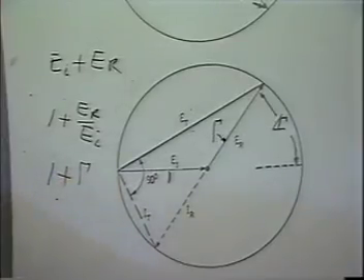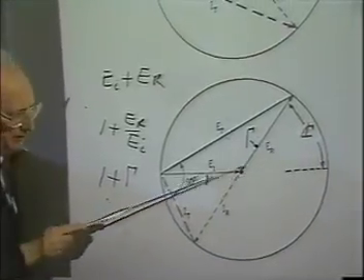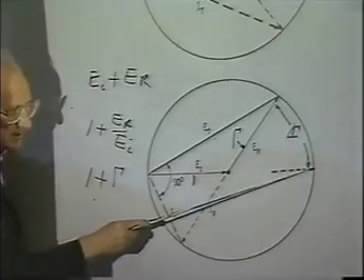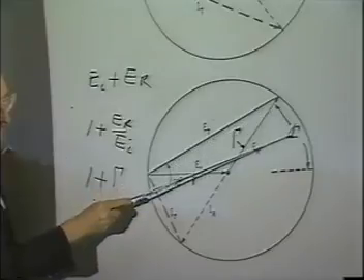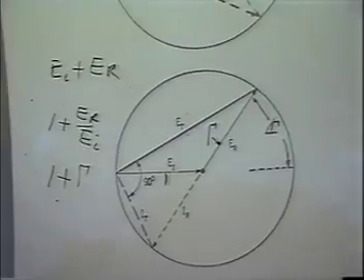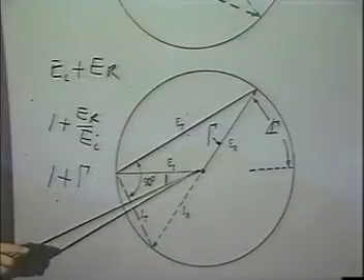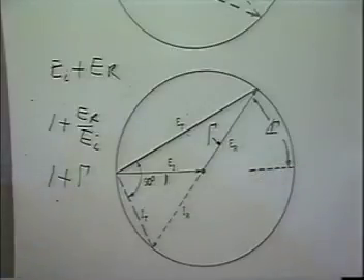Now, the angle of gamma is measured from this point. Here, the two are in phase, right? If you measure counterclockwise here, this is gamma at an angle here, angle of gamma, and you go round this direction, and it gives you the angle between the reflected and the incident voltages. Because notice, E sub I, E sub R out in this direction, they are in phase, so this must be 0. Later on you'll see this on the chart, and we'll do some actual plotting. Plot these angles of reflection coefficients so you can see it.